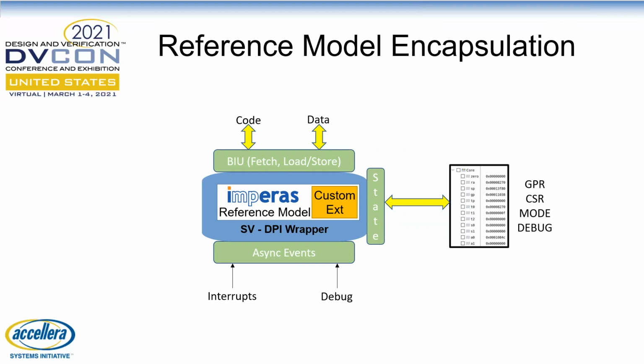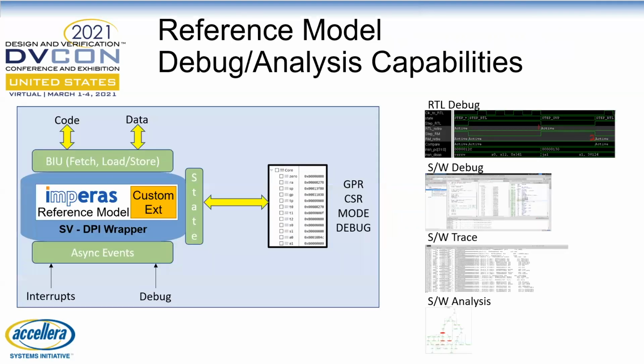For example, if the core had support of the F and D extensions, then they would provide floating point registers, both single and double precision. If we had support of the V extension, then this would also provide the vector registers as part of this shared data. And inclusion of the X subset for custom extensions will also provide visibility of custom registers where they were applicable.